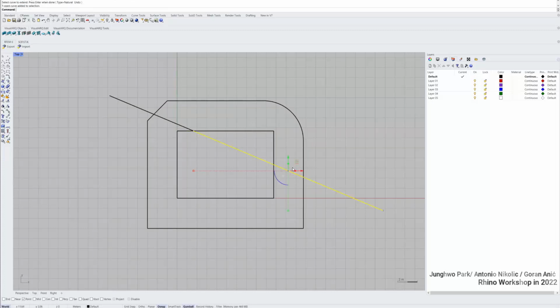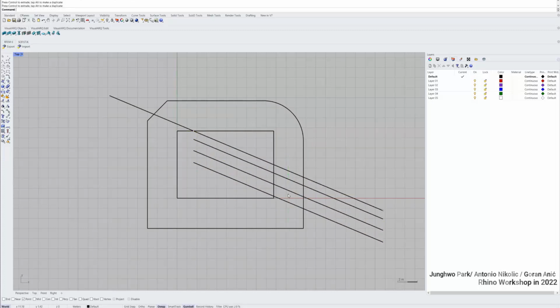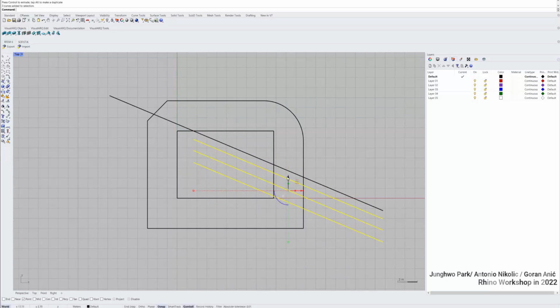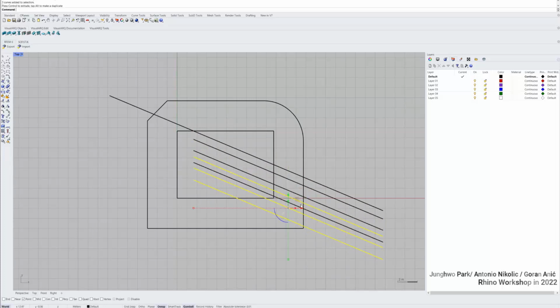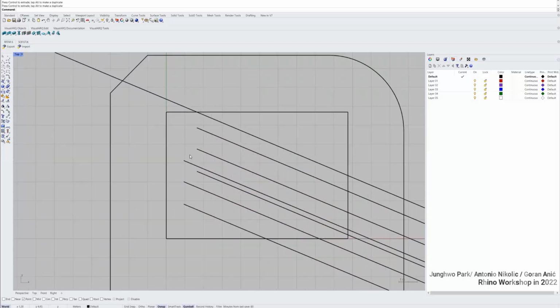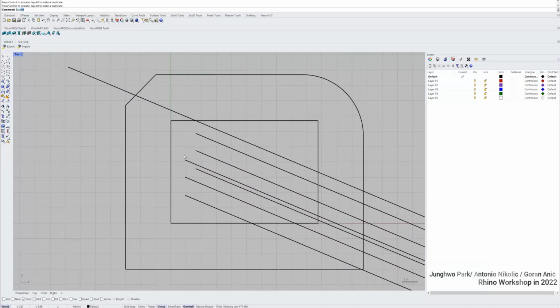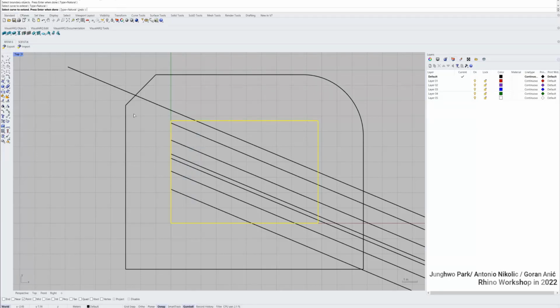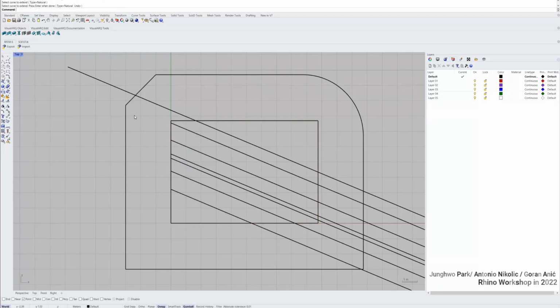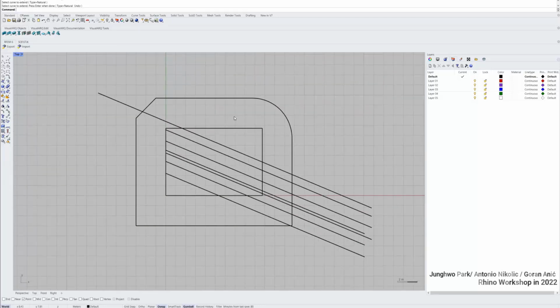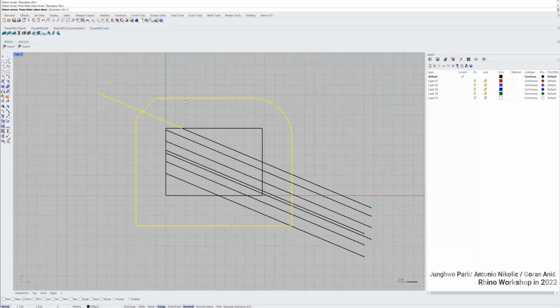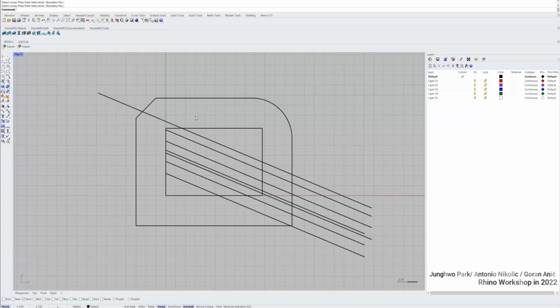as you can see. If you have more than one line that you want to extend, it doesn't matter if they are different lengths, and we can do extend, hit boundary, and when you select them, they are all extending. It's nice, eh? So a lot of things. So for example, here I want to draw hatch. So you can do the hatch command, and you want to select the boundary, but we don't have one. You need to have a closed boundary for the hatch.